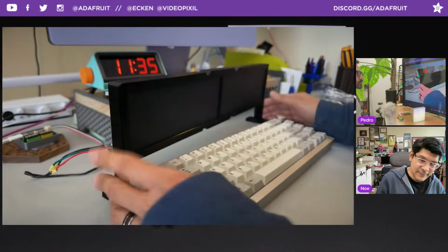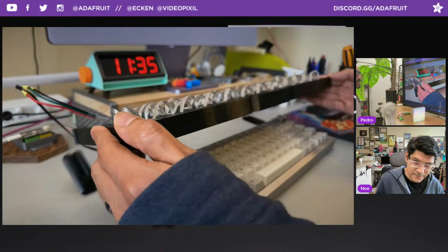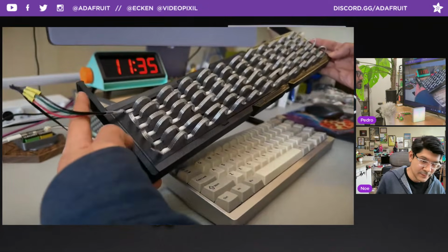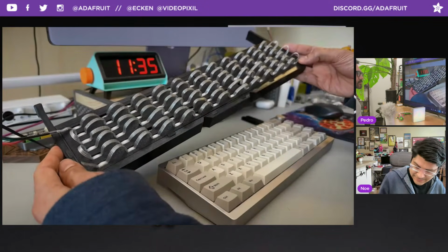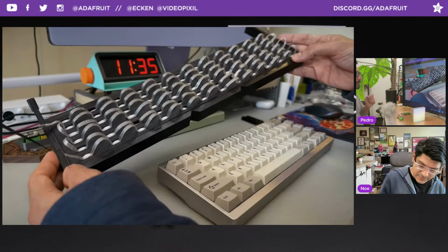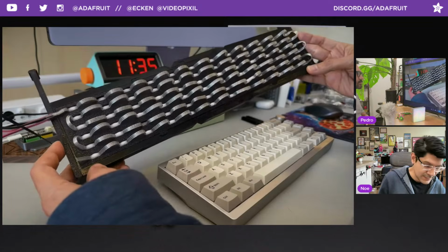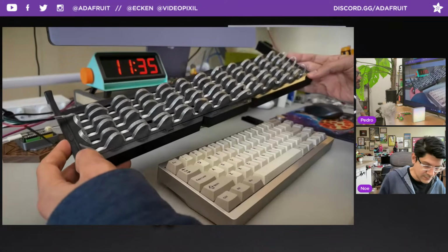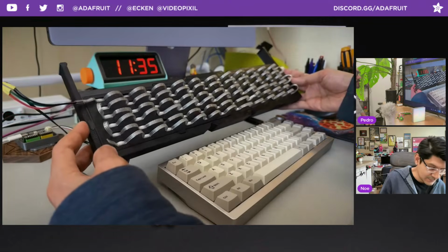So the latest thing is I got rid of all the screws, so everything just snap fits together with these dovetails right here. And we're using the NeoPixel Seed/Pebble Strand. So the idea is you just pop these individual NeoPixels into the little holes here that's a part of the grid. And that way there's really no soldering required for the individual pixels or strips.